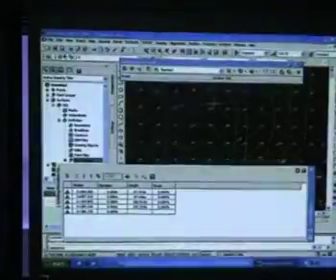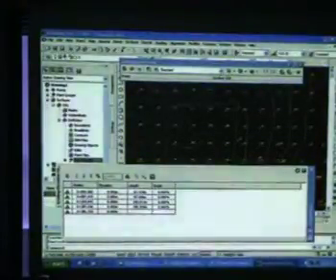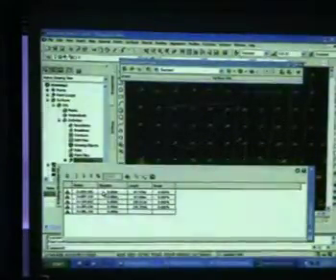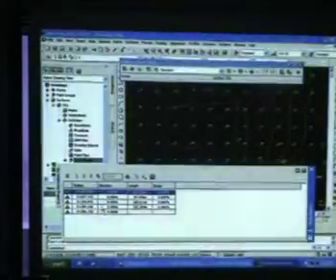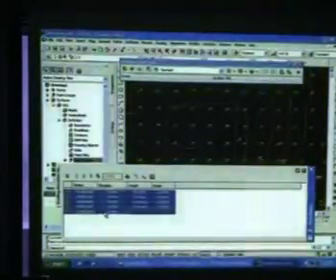A window will appear, and this is where you modify your elevation. Let's say we want to make this a flat platform. So I'm just going to click the first line, hold shift, and then select all the way down to the last line.